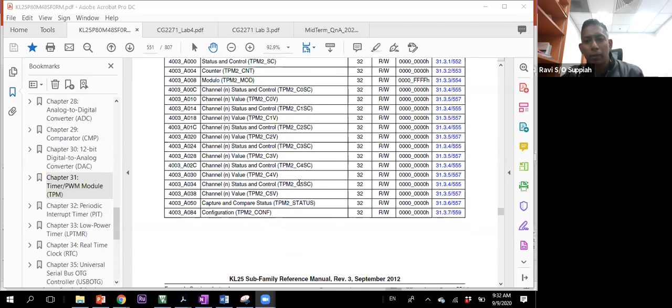Before you think of all the things you want to do, be very mindful of the fact that what is available at the microcontroller level may not be available at the board level. We always have to be careful that not everything is available on the board. That means we need to see which pins are brought out to the header connectors that we can tap onto.